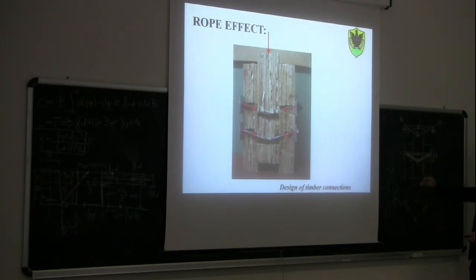So in the end, this system induces on the specimen one force which is applied in this way on the specimen itself. So this red force here is a compression force equal and contrary to the tensile force that I get in the dowel, and this compression force will be applied from the washer directly to the wood itself. Okay? It's clear? Now, what is the effect of this compression force on the specimen?